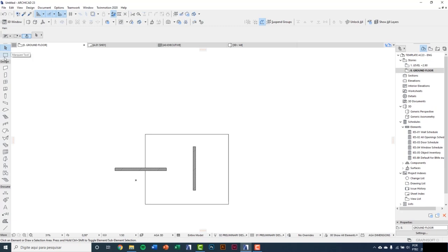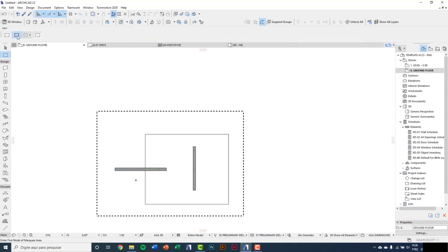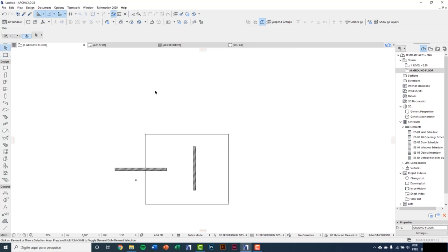It's this rectangle. It is a fixed selection. So here you can choose between the single floor option, the single selection, or the method for all floors. So using this first one, it selects just the elements on current story. I'll put here rectangle option. You can click Ctrl A to select all, just in this floor. And using this other option, you can select the elements in all floors. Press ESC to exit, and it's done.